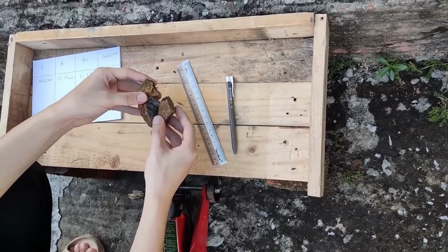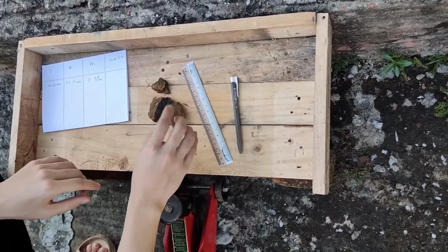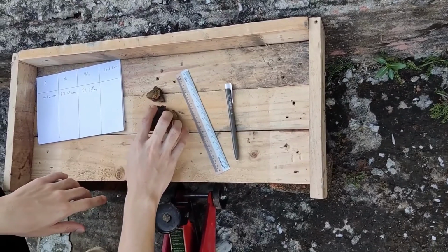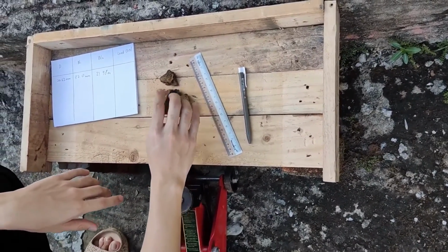After we subject the rock sample under pressure until failure, we will record down the load that we have applied to the rock sample. Then we will use a series of formula to determine the IS-50 point load test index of the rock samples.